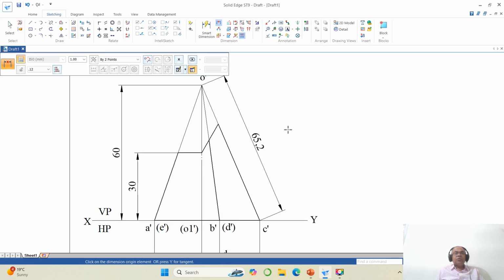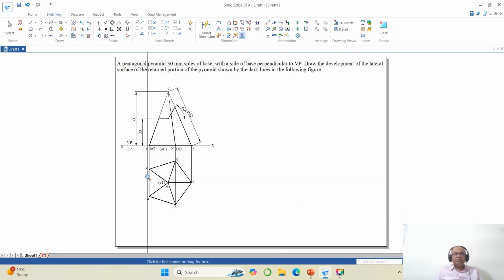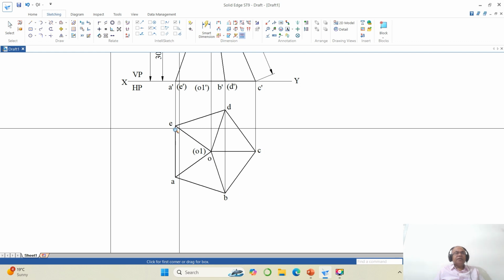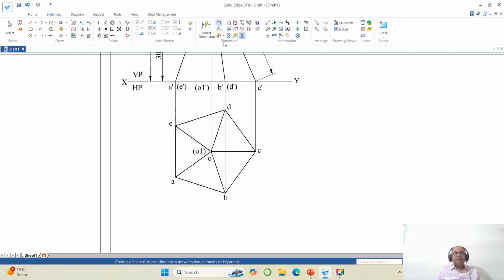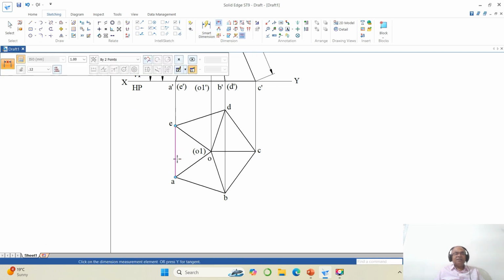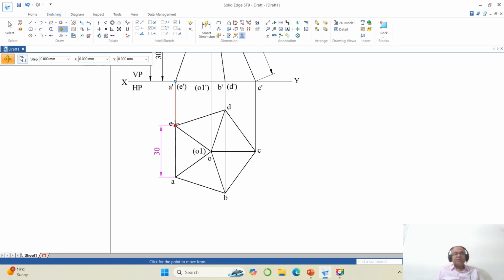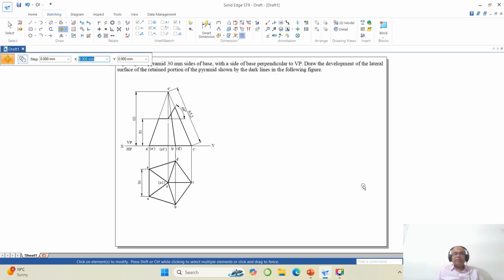Then you go to angle between, select this line and this line. So you have 60 degrees. You take that. Okay, then come down to fit. So come down to zoom window. Here you give the distance between this line to this. You're going to get 30. Yes. So now you go to move command, select this. Okay, now everything is given in the dimensions.